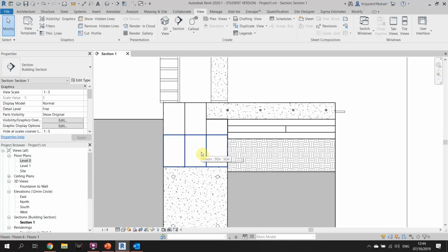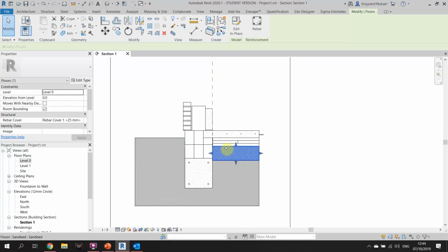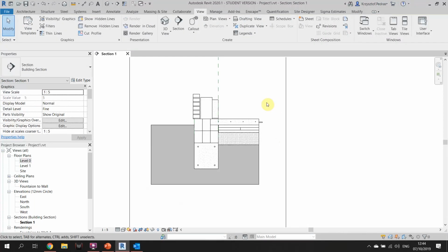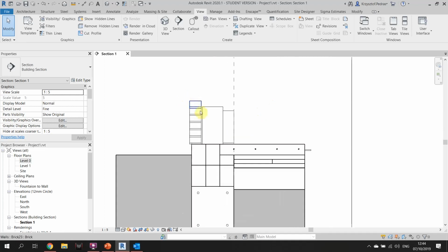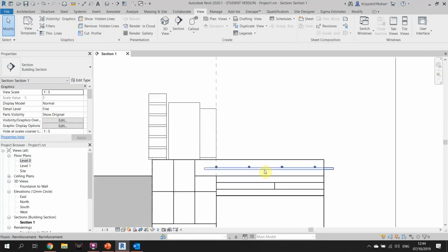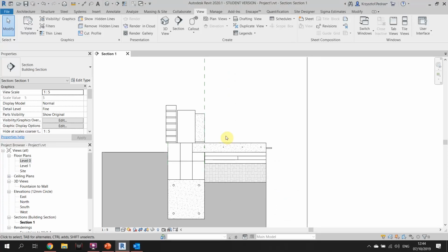A lot of information in it, starting with soil, sand. You get the hatch patterns, for example. And there's two ways to do it, how to annotate properly, because everything needs to have a pattern. If it doesn't have a pattern, by default, like how people understand it, architects, it means that it's empty, right? So if that's insulation, it can't be empty, because it is a material. Like here you have an air gap, so it can stay empty because that's just air, there's nothing there, right? So you have to make sure that every material has a hatching pattern.